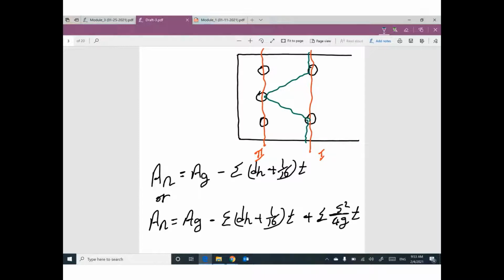So we have 3 expected failures. I believe number 1 is not critical because number 2 is more critical. Do you know why? Because number 1 has only 2 holes, but number 2 has 3 holes. So section number 2 will be more critical.